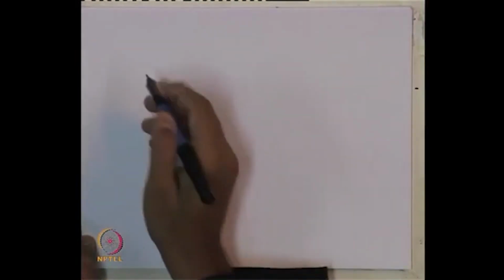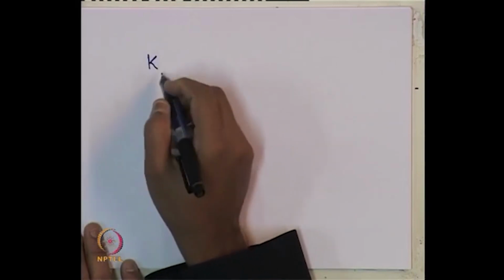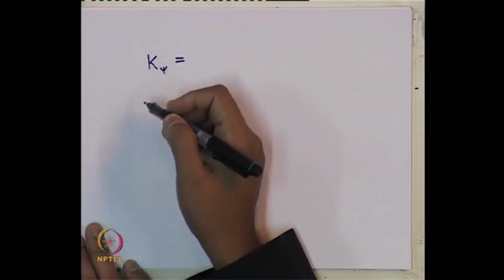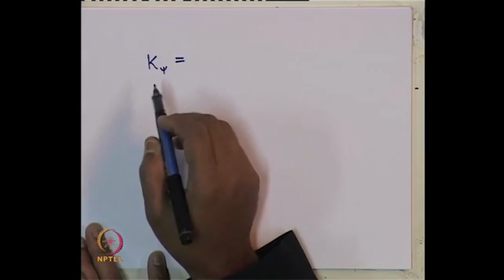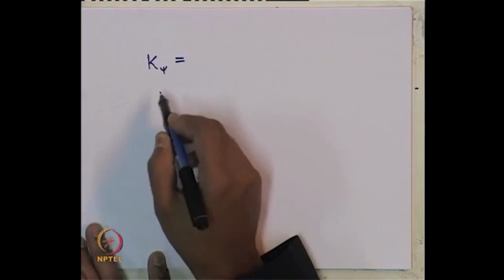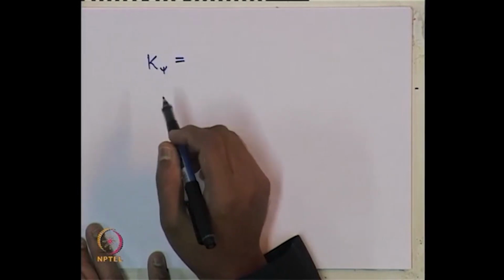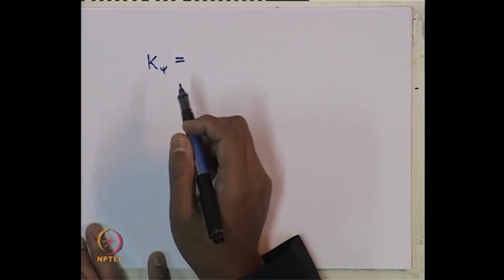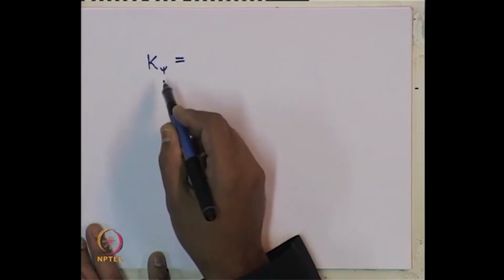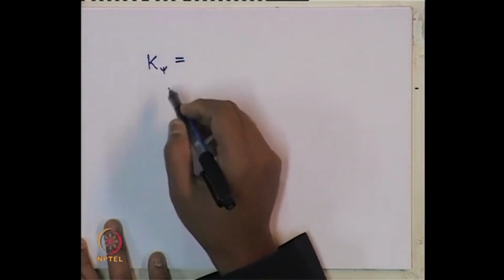And from theory of elasticity, to obtain the expression for k, let us denote it as k psi as for rocking. Earlier we have mentioned k psi for yawing. So, now I am changing the symbol. It is just the change of symbol, nothing else, but still we are discussing the rocking, because in Richard's book, where we are finally checking the dimensions, there k psi is used as a rocking symbol. It does not matter, it is just the matter of symbol.